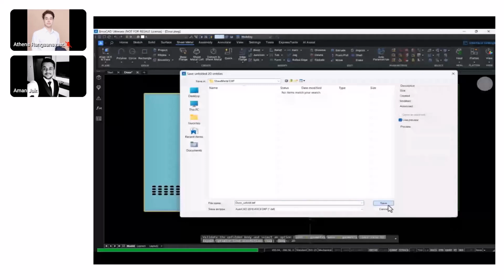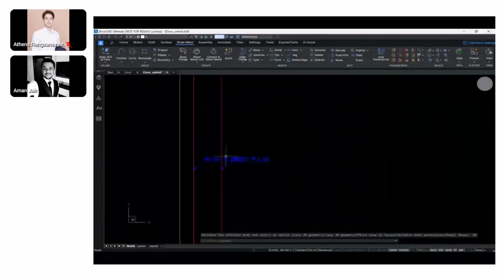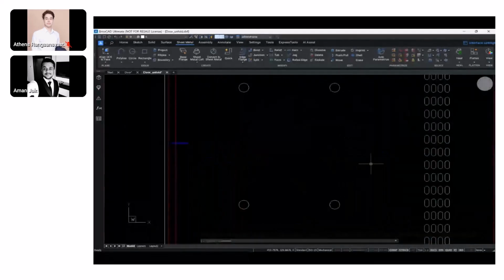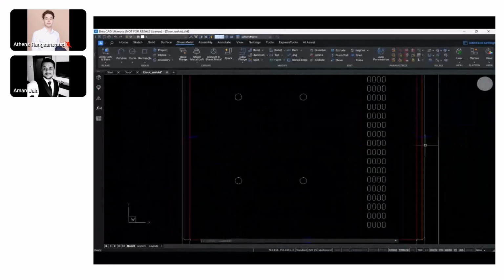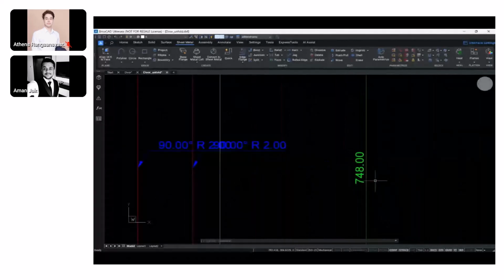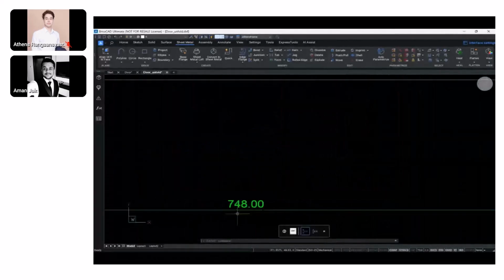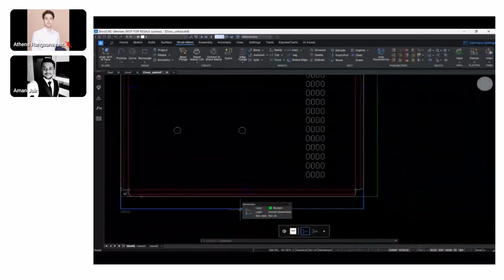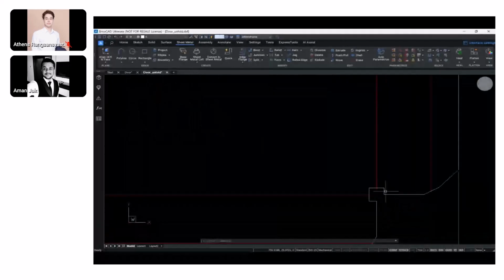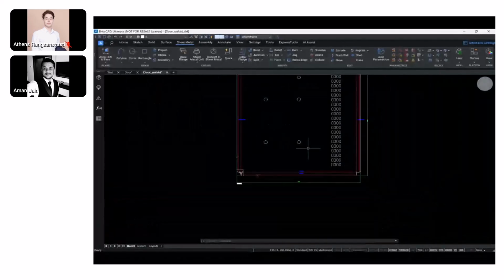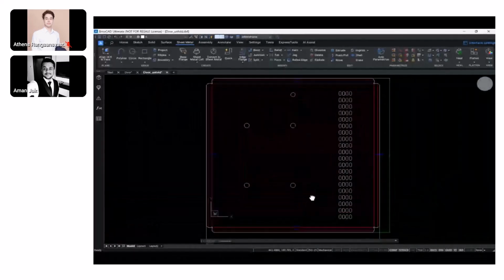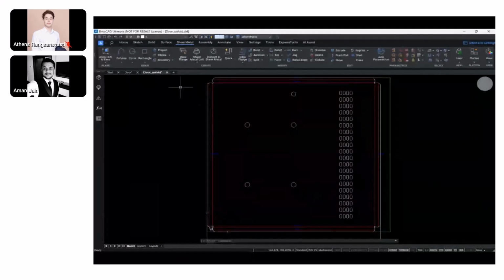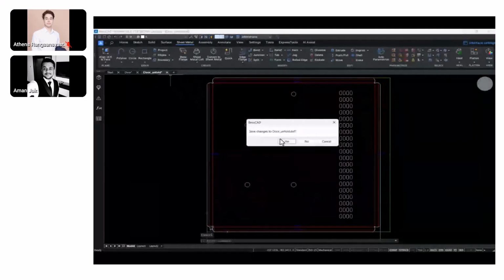As we looked at in the process, where we need an input from the CAD software to the machining software, this is the one that's most widely used. This can be used in most of the CAM softwares worldwide, and then the machining codes could be generated on top of this. As you can see, the bend lines, the representations, and the reliefs have automatically been created for the DXFs that we have in place. Let's save this.